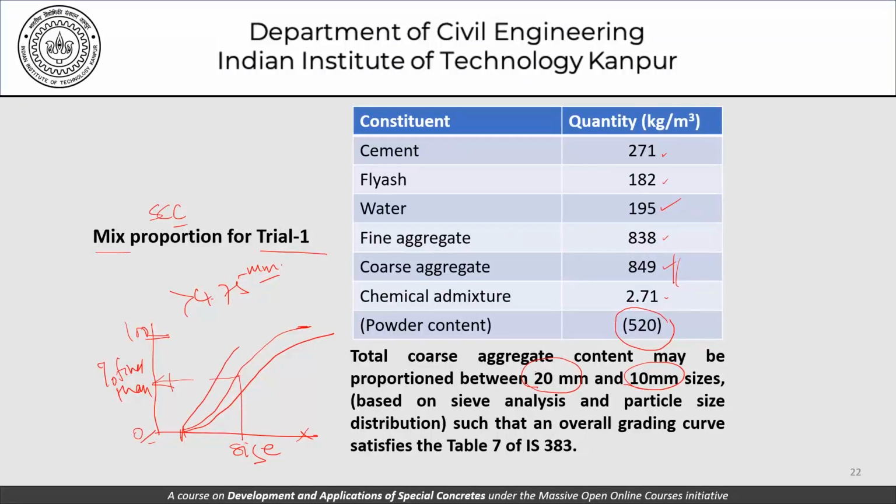It is known that after all, when we are buying or when we are getting aggregates into site, it is not possible every time to come to a particular value for a particular finer than value. Therefore, we are given a certain range here or a certain range here, whichever way you want to look at it, that okay, so long as particles finer than 10 mm is concerned, they should be at least 50% or 60%, in the range of 40 to 60% or the range of 45 to 55%. So that is how we try to specify this.